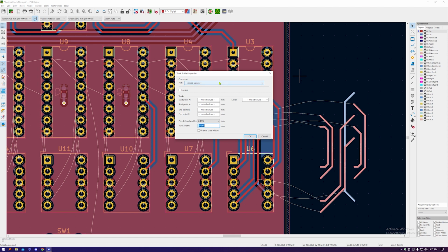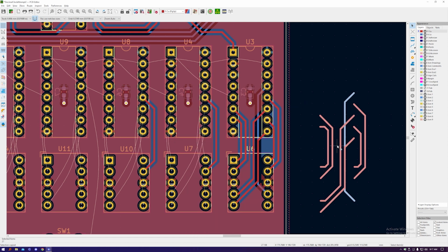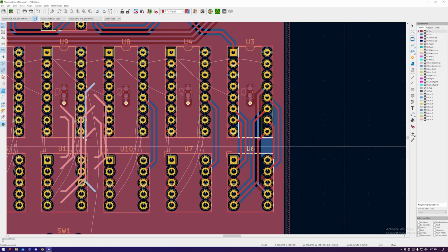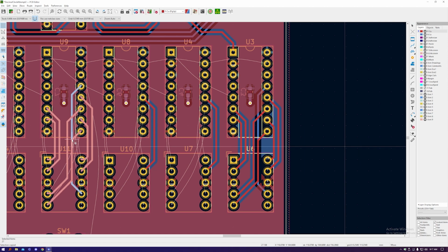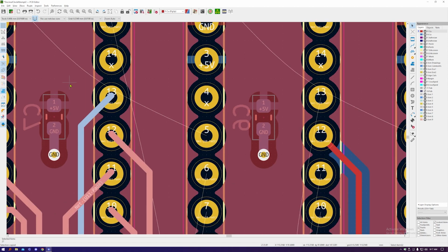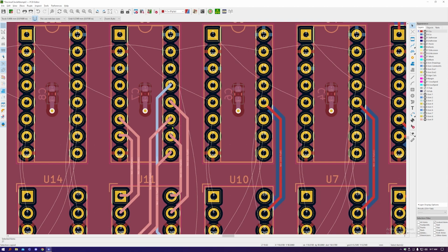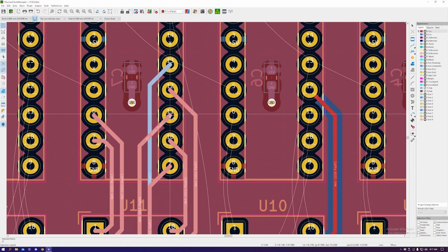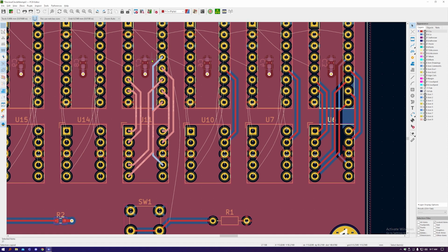There we go. Mixed values net. So then just do no net. Okay. Now they're not trying to link anymore. Then drag this all the way over to here, which is where we want it to go. For some reason it's got a strange offset, which I think is to do with the reference, so just make sure you're dragging it from the end of one of the traces and then it will stick to the grid how you'd expect it to. Then press B, and yeah, it works.